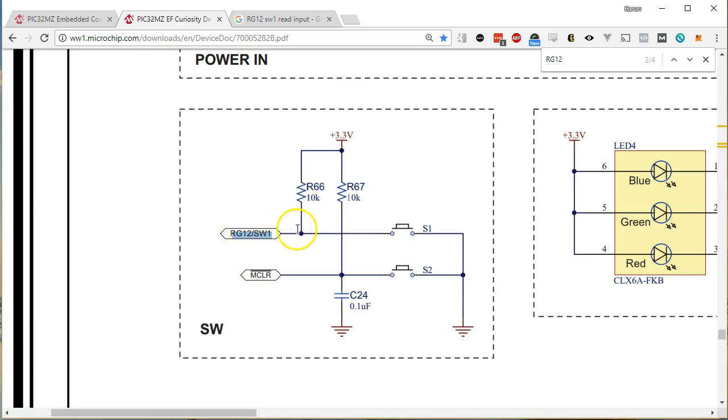The other thing that could happen is if you didn't connect this pin at all, the voltage that can be read off of it has more to do with capacitance or static electricity than it really does with what's connected to it, because there's nothing connected to it. So you can get some really weird things with these non-grounded pins. So usually that's what they suggest: for any pins you're not going to use, you just ground them out so that they're always pulled to 0. Otherwise, you can get some weird things as far as static electricity, static discharge.